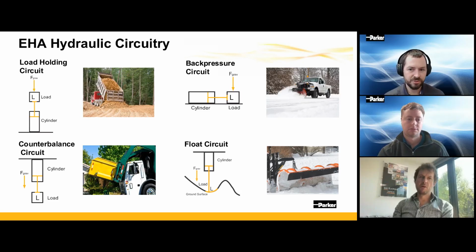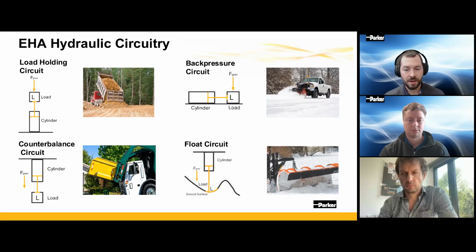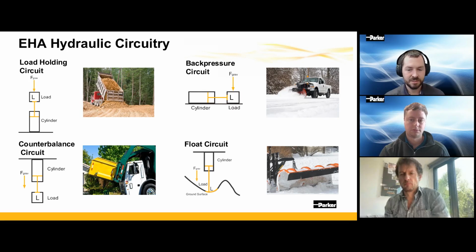You've seen back pressure circuits. These are great for steering or tilt control where you've got some resistive load and then you've got a lock in a position. Bottom left there, counterbalance. You might be aware of issues on hydraulic systems where if you've got a tension load and you're extending, you can overrun valves or the pump. Typically, counterbalance valves are used to have more smooth or safe operation. Those are things that you can get in EHAs now.